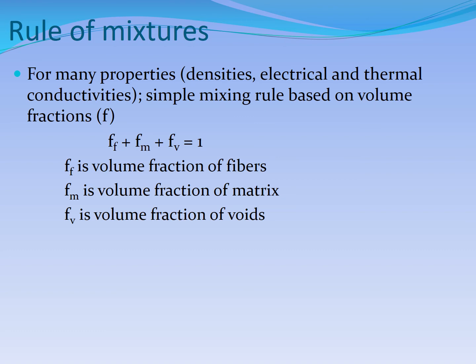So this is a very, very simple equation, linear equation, but very powerful, and we use even this in simulations. When we try to simulate the behavior of a composite using finite elements and so on, we still use this very simple rule of mixtures.